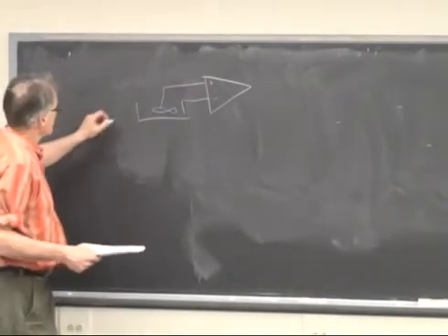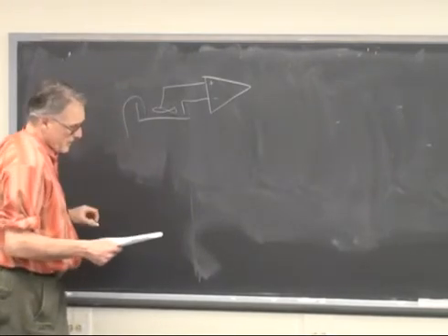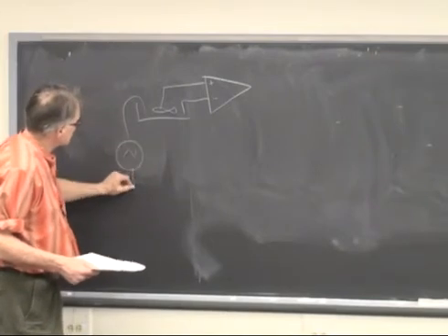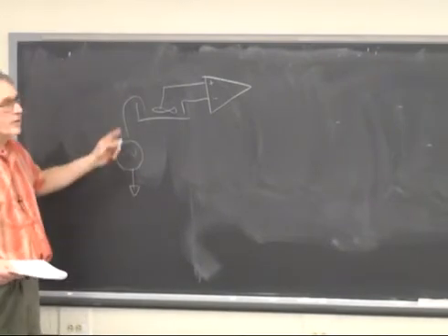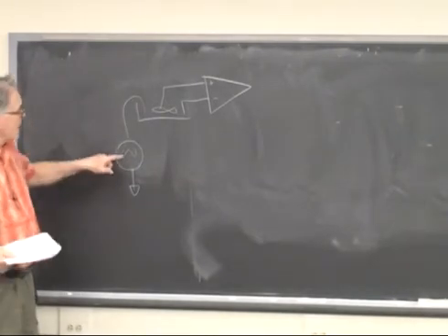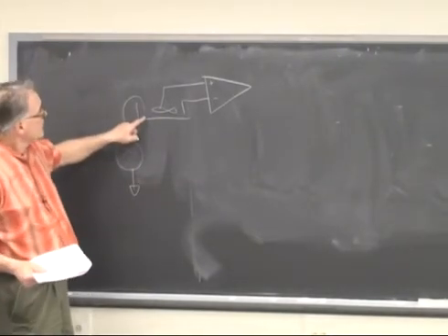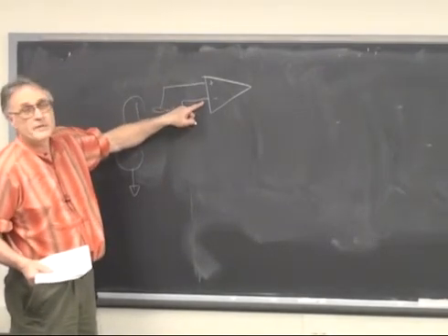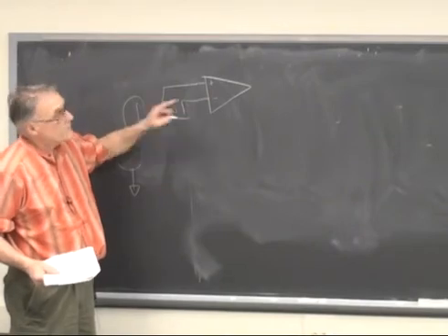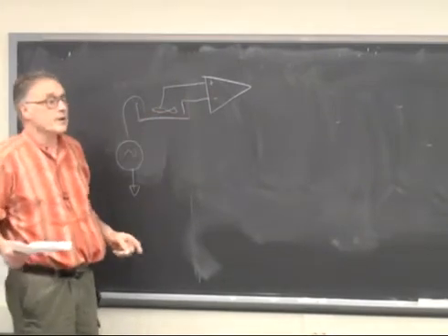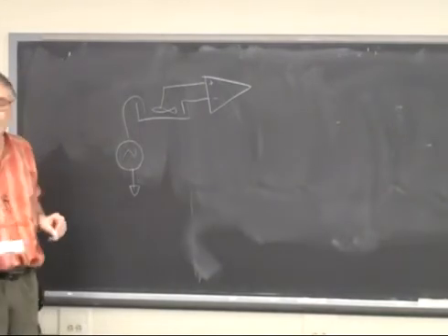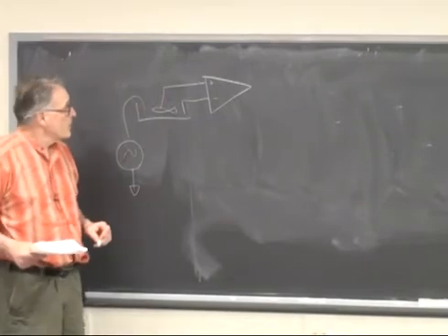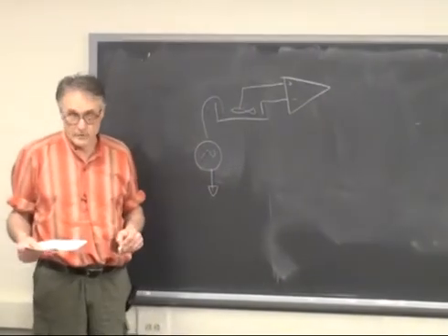And then there's a ground lead that goes out here, and there's some small resistance, but there's also a 60 hertz AC noise pickup from just the environment. This 60 hertz is now referred to as a common mode voltage in the sense that it is applied to both the positive and the negative input of the differential amplifier. And if the differential amplifier is a perfect subtractor, this noise completely disappears. And so, which is referred to as having good common mode rejection.